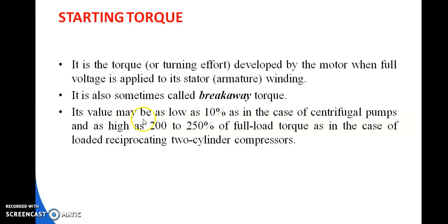Its value may be as low as 10% as in the case of centrifugal pumps, and as high as 200 to 250% of full load torque as in the case of loaded reciprocating two-cylinder compressors. So remember, these can be the variations in the starting torque values.